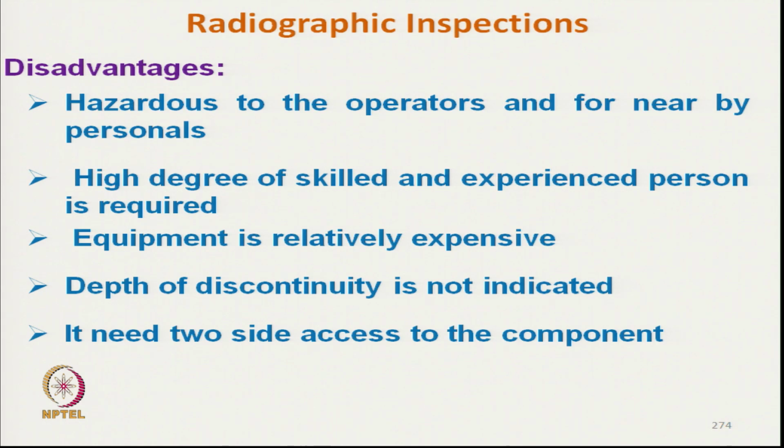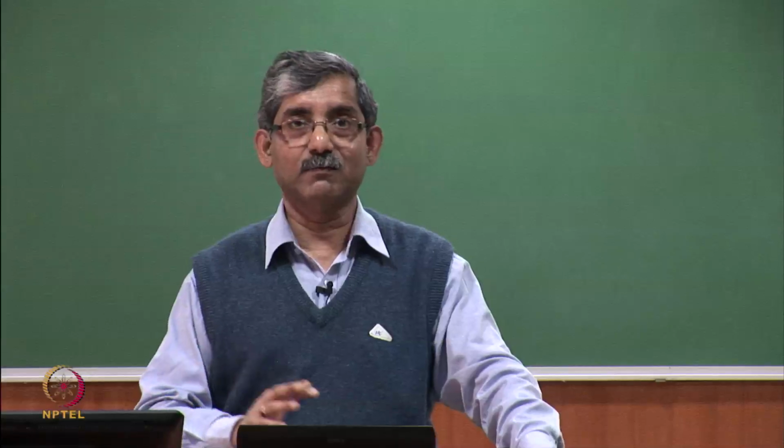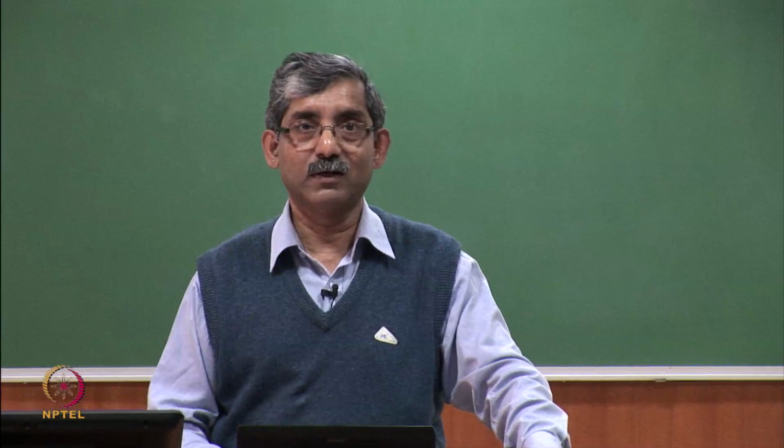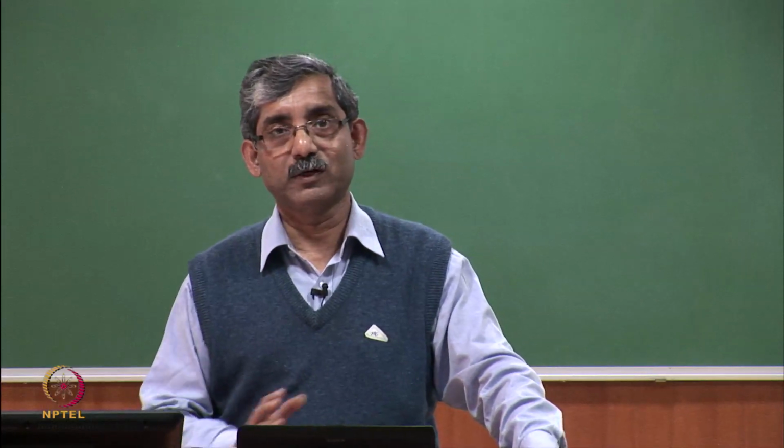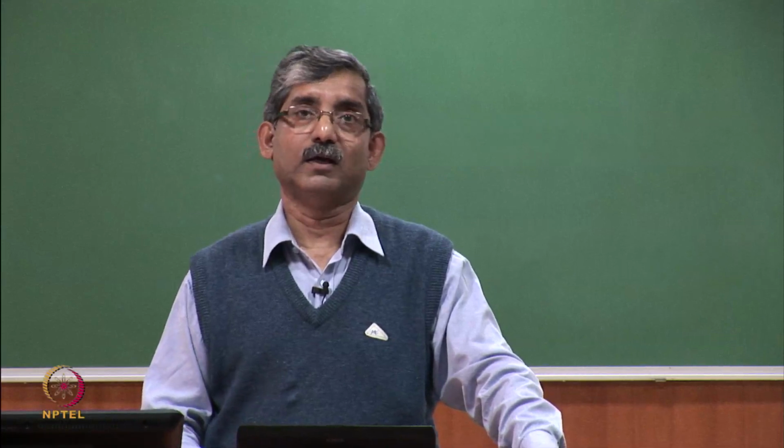The main drawbacks: it is hazardous. X-ray and gamma ray pose a human health hazard risk. The person testing needs to be highly skilled, the testing is expensive, and it needs two-side access to the component. It does not work in reflective mode, only in transmission mode, so we need access to both surfaces.